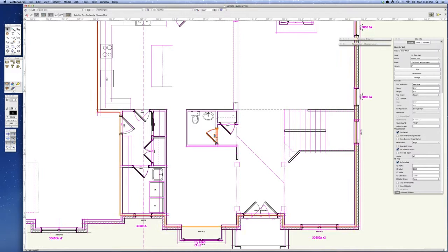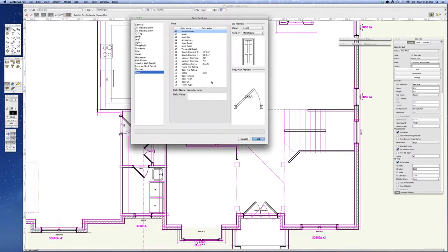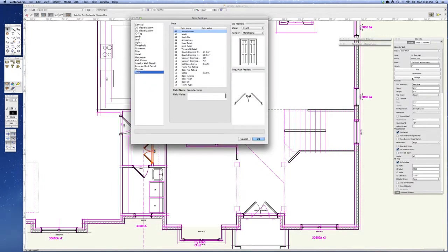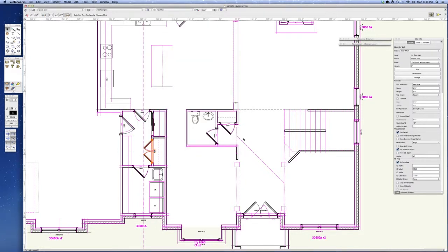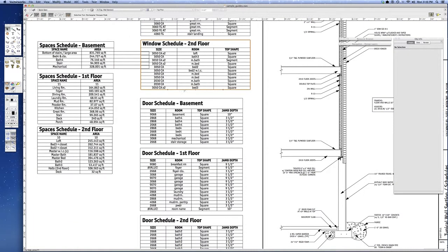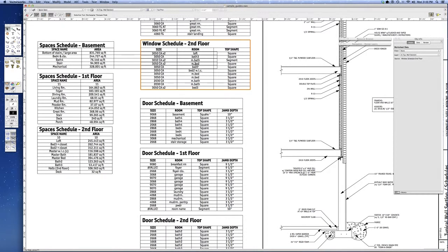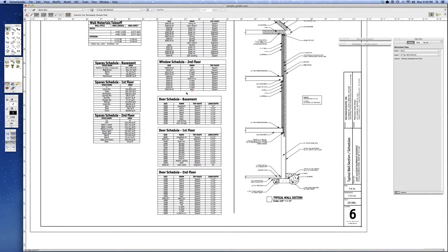All right, let's just do one more. This should be the powder room, first floor, powder. Okay, this should be mudroom closet or something like that. Mudroom. All right, so I enter all of those data fields for windows and doors. And then I simply have to go to these. I can right click, I can hit recalculate, and then it will fill in all of these room values that were previously not filled in.